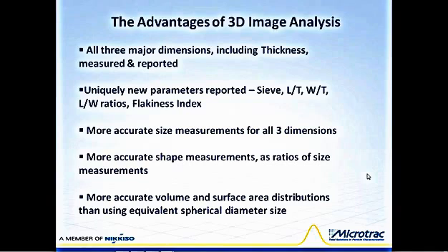And in 3D mode, individual particle volumes can be calculated as the product of length, width, and thickness, giving a volume distribution that isn't dependent on particle shape or orientation, as is the calculation of equivalent spherical diameter reported as a volume distribution.